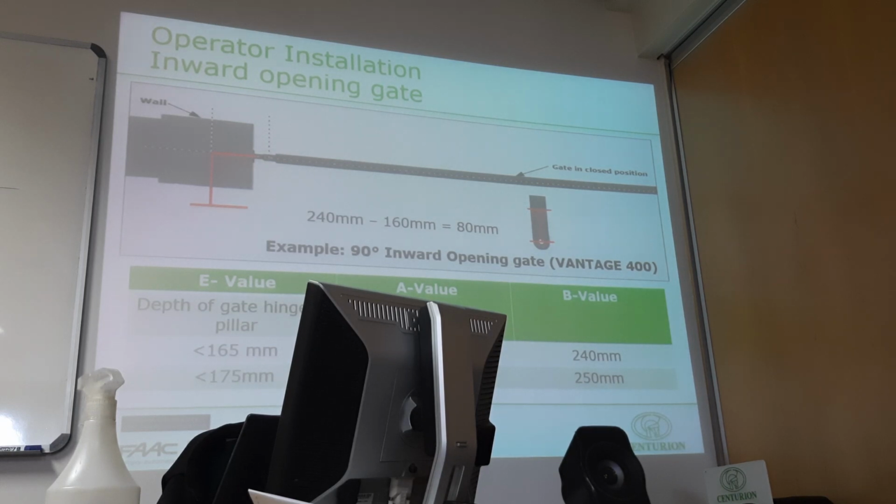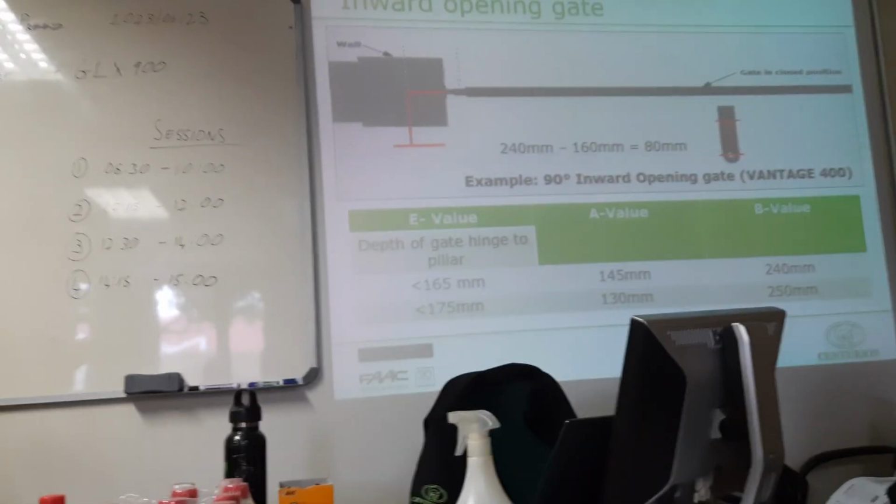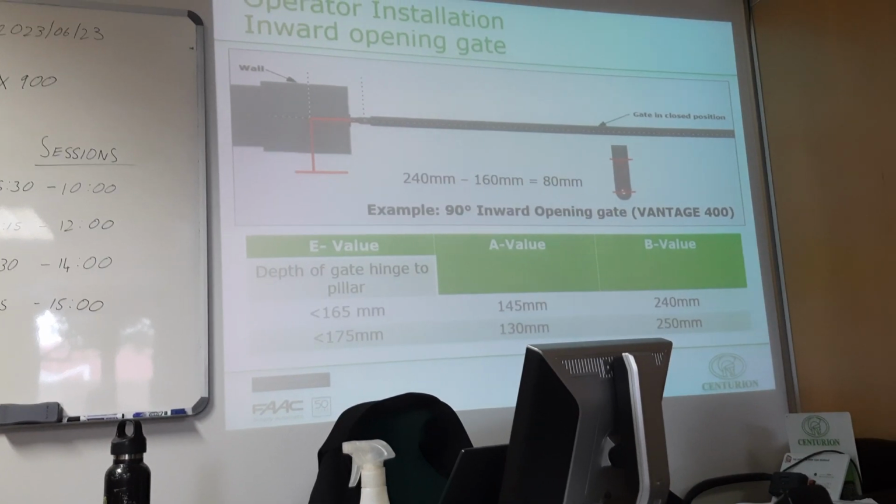But you say, no, I'm installing a gate lock. So I'm not so worried about the strength of this motor stopping someone from pushing it open to get access to my premises, because I've got a gate lock. So I can make my B value a little bit less to make the motor faster, because now my A value is bigger and the motor can be a little bit faster. But I'm taking away some security. If I've got a gate lock, then the security is not so much of a compromise. On its own, the motor can't resist when someone is pushing it, except if it's having an automated lock. So we've got positive close mode that you can have enabled, but then you need to have a pin in the middle on the ground, on the paving. You need to have like a flat bar or